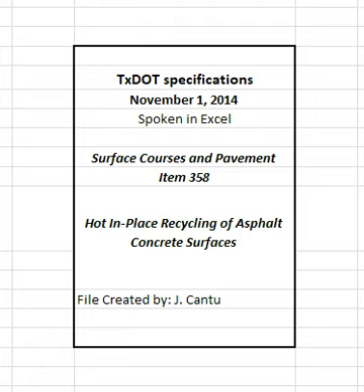4.2.2 Job Mix Formula Approval. The Job Mix Formula, JMF, is the combined aggregate gradation and target asphalt recycling agent percentage established from the laboratory mixture design. 4.2.3 Hot Mix Asphalt. If the process requires new HMA, use materials meeting the requirements of Section 340.4.3, Mixture Design, or as shown on the plans. Document in the JMF the percentage of new HMA used in the laboratory mix design submitted.